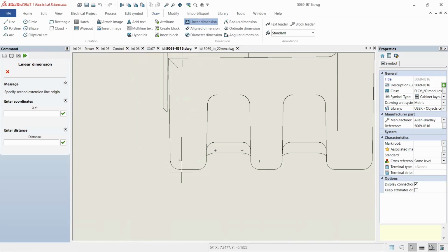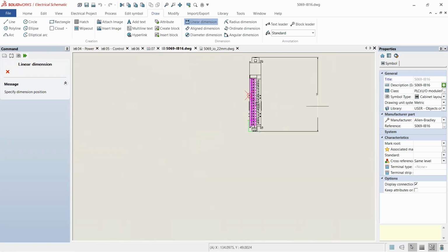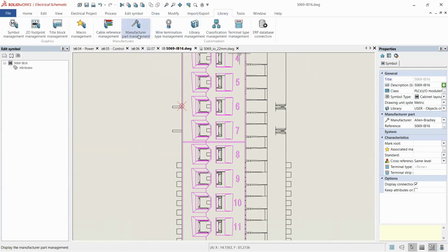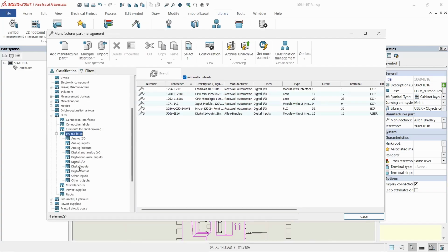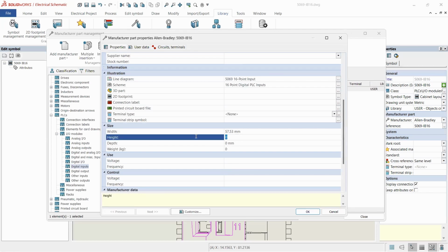And down here, I can probably get one of these flats, which is the low point, which is fine. And 144. 144 even is what we're going to go with. Library, Manufacturer Part. And again, I recommend doing it off of the drawing the way I'm showing it right here. 144 before I forget. I recommend doing it off of the drawing rather than off of a PDF, because the PDF often doesn't account for those little things like locking tabs or the pins that stick out the side or whatever, but SolidWorks Electrical does.